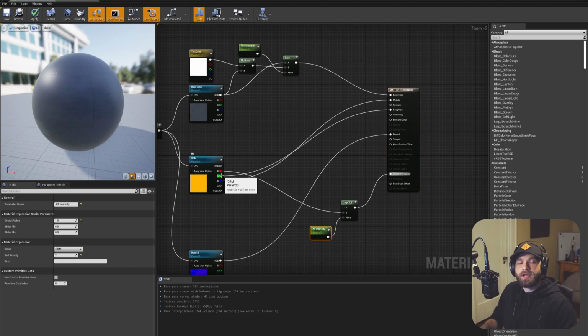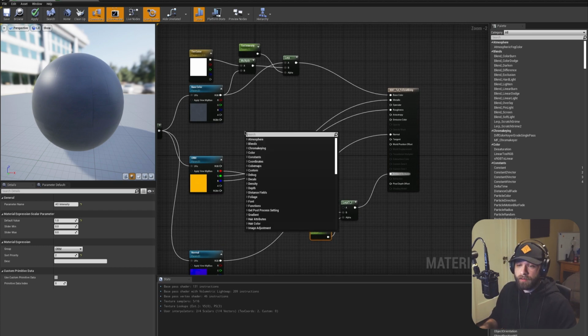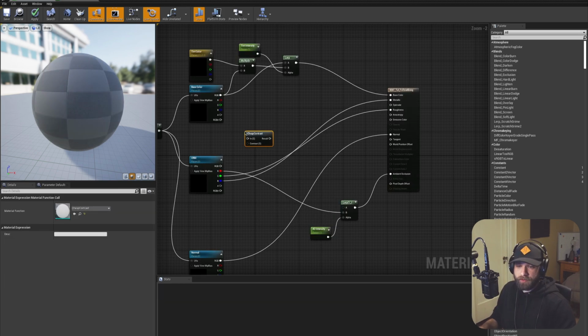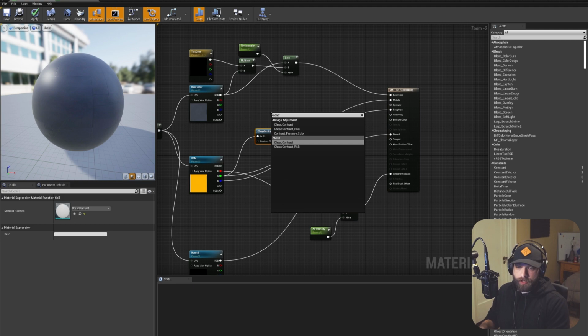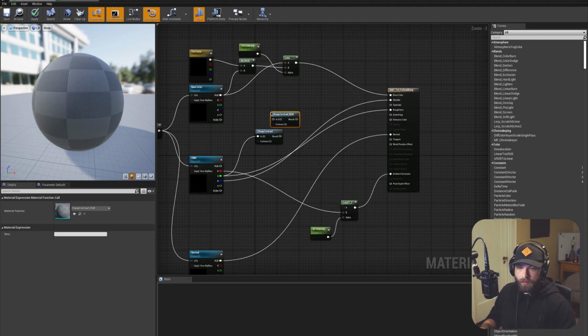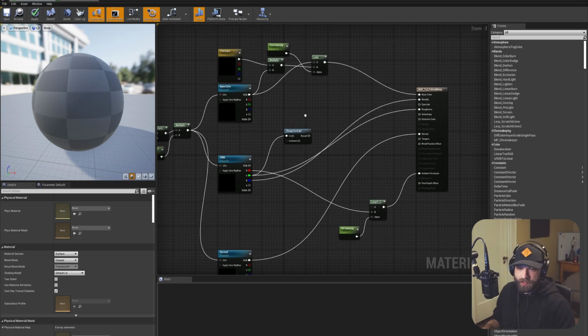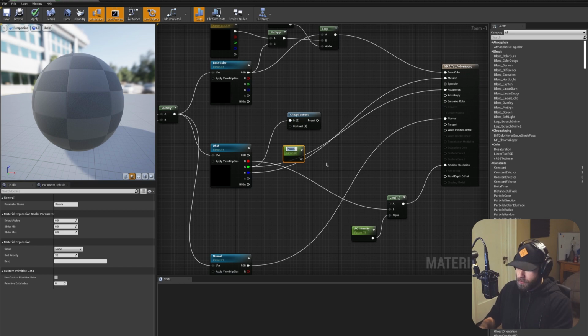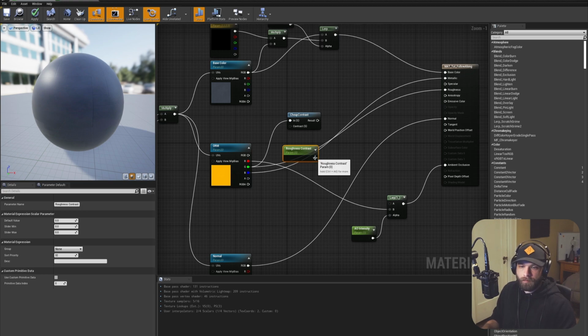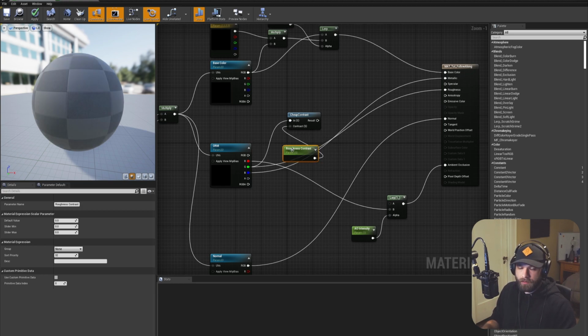And the very first thing we're going to do is we're actually going to introduce a contrast node. So there in Unreal by default is a cheap contrast is what it's called. And you plug in a channel. There's one that's individually one for grayscale, and then there's also a color contrast that's for color nodes. So obviously in this case we're not going to be using the colored one, but we're going to create a parameter. I'm going to call this roughness contrast